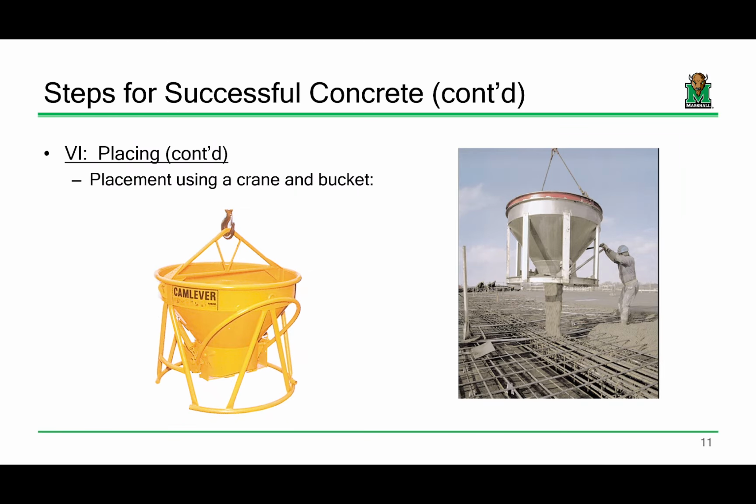Okay. Another means that you can place concrete is to use a crane and bucket. I'm curious if anybody who's ever been on a construction site has seen these. You've seen them, yeah. I've used these as well. You can usually place about a yard at a time. A 3/4 yard bucket's pretty common. A yard bucket's pretty common.